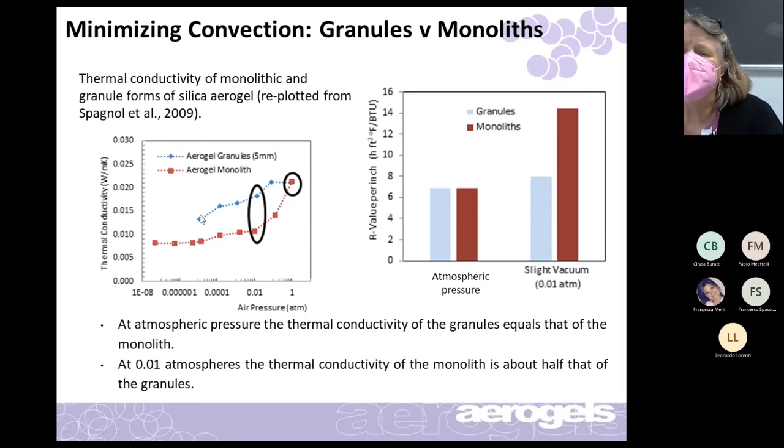When you reduce that pressure, the thermal conductivities of both materials decrease. But the thermal conductivity of the monolithic form of the aerogel decreases even more.